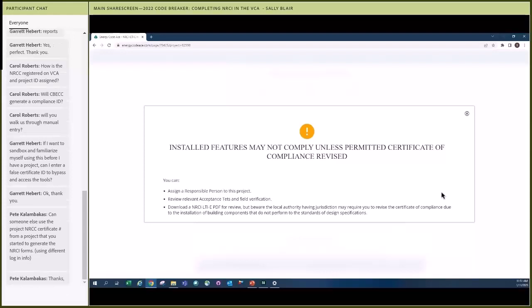This is why we should be doing this at submittals. I would note my substitution, print this form out, and send it with my submittal package to the lighting designer. I would say, whatever reason, it's going to be way cheaper if we use fixture L5 in this space than fixture L2, or whatever reason you have for the substitution. But it's more wattage, 108 watts instead of 90. Does 108 watts still comply?